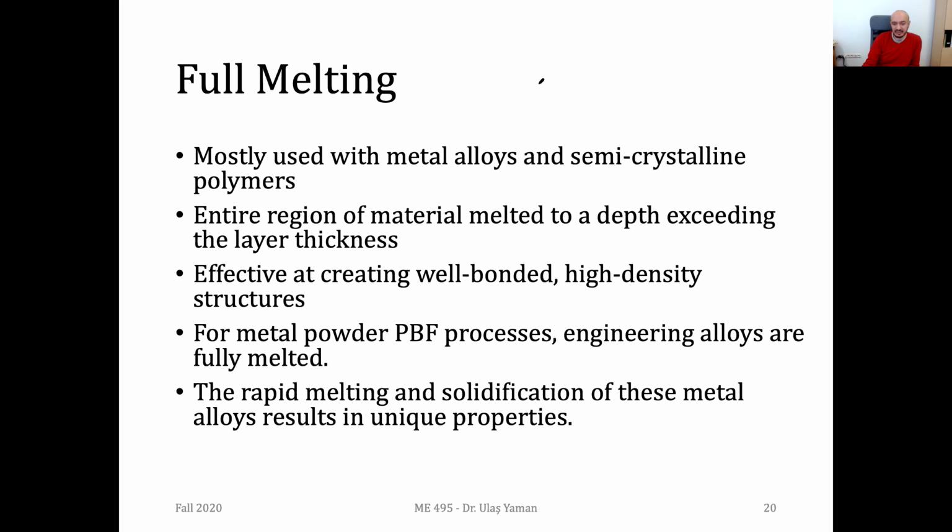And once you have rapid melting and solidification, you will mostly have better mechanical properties compared to the casted products. The strength of these additively manufactured products will be a bit better than the casted products since we have rapid melting and solidification.